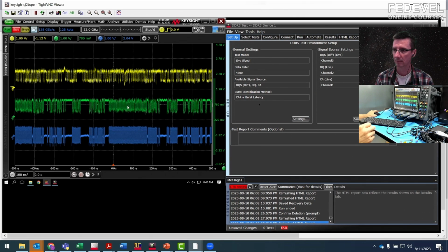It's a little bit smaller. So I would attribute this to the write cycle. But we may need to confirm this, correct? Exactly. The voltage should be the same for processor and memories in theory, but it may also depend on termination. So we should confirm this, I guess.